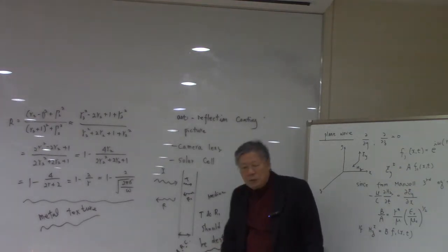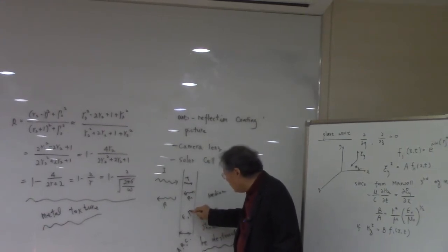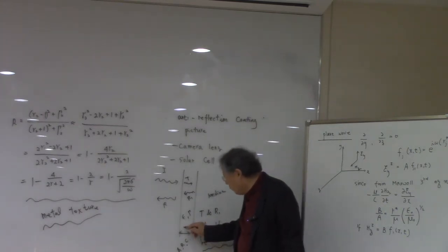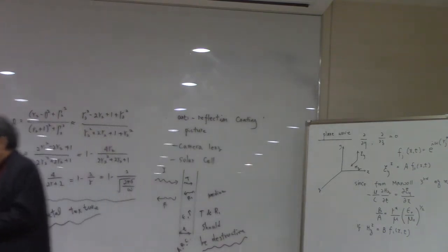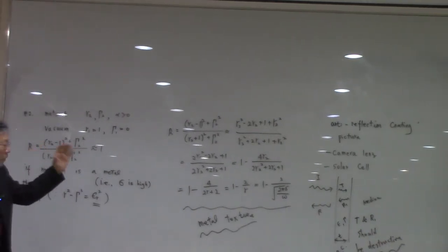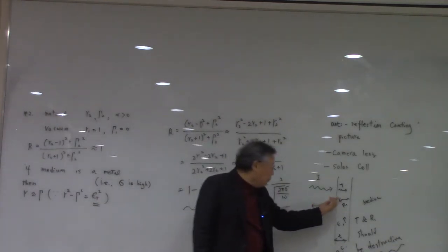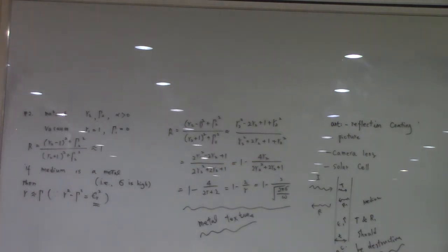Okay, by manipulating the dielectric constant and the gamma values of this anti-reflection coating. And then basically we have to work on the thickness as well. And then we can calculate the proper thickness of this anti-reflection coating to make the reflected beam go to zero, make the reflected wave amplitude zero.